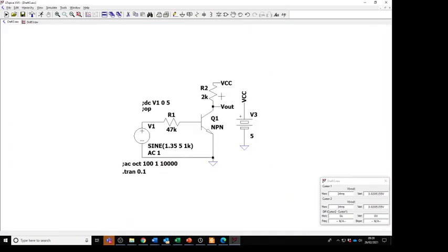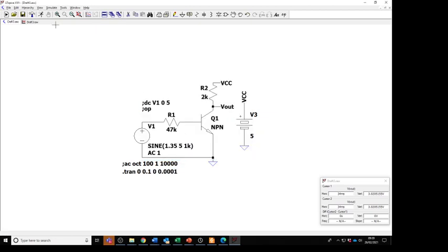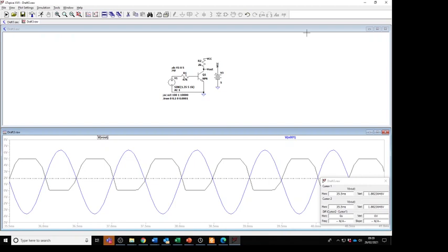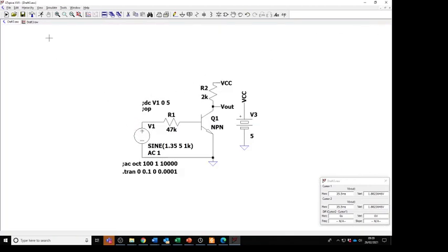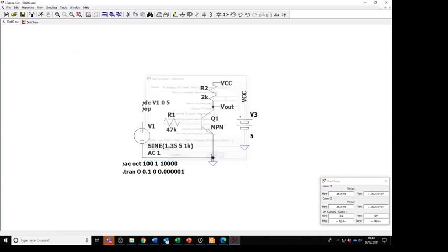We can solve that if we're interested by specifying a maximum time step. So this makes it do more calculations, and again you just have to sort of guess what we want in there, but it says that it's going to do it every whatever fraction of a second that will be as a minimum. So it should take it longer if I've got the numbers right, but hopefully it didn't take it much longer, did it? So I need to go a bit further on that. Put another couple of noughts on.